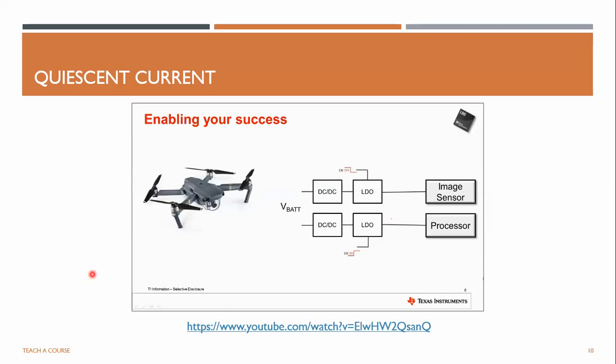These small devices are not just limited to consumer electronics either. They play just as big of a role in industrial applications such as smart meters, building, and factory automation. So even though designers sometimes overlook quiescent current, they can ultimately make the difference in an application running for a few more seconds to days or even years. Now that you've learned the importance of quiescent current, make sure to always account for it in your power dissipation calculations.